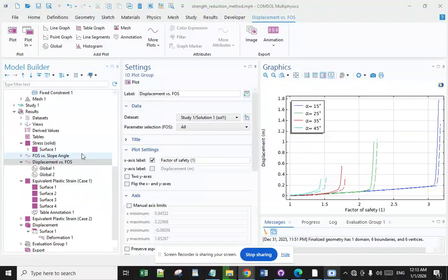Yield and ultimate calculations. For ductile material, for example most metals, it is often required that the factor of safety be checked against both yield and ultimate strength. The yield calculation will determine the safety factor until the part starts to deform plastically. The ultimate calculation will determine the safety factor until a failure. In brittle materials, the yield and ultimate strength are often so close as to be indistinguishable, so it is usually acceptable to only calculate the ultimate safety factor.